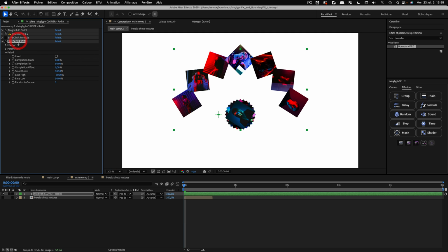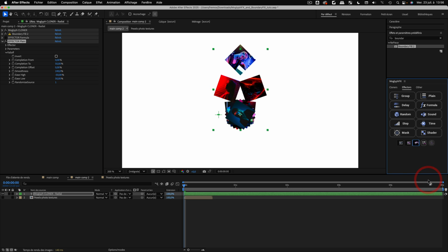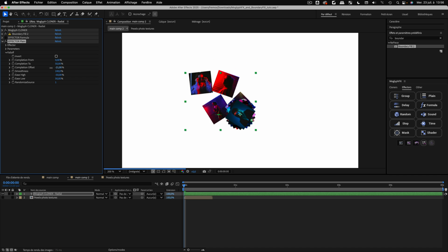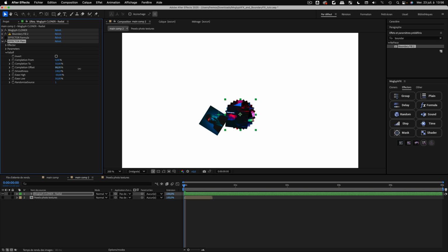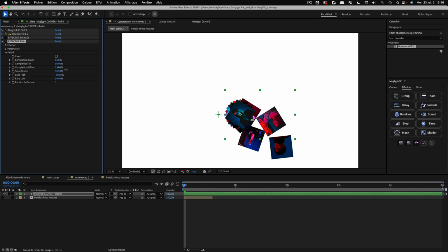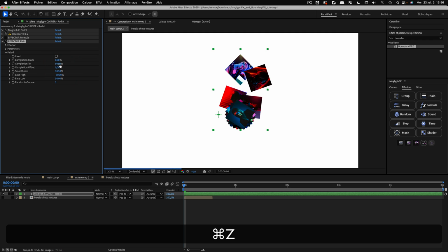And if I want to, let's say I stick with 50% completion, if I select my plane effector and go to the MoGraph Effectors tab and change the falloff shape, which is square falloff by default, I can select something like smooth falloff, for example. And now if I play with completion offset, I can create really nice animations like this, just as you would shuffle a playing cards game, right? So very, very cool effects also.